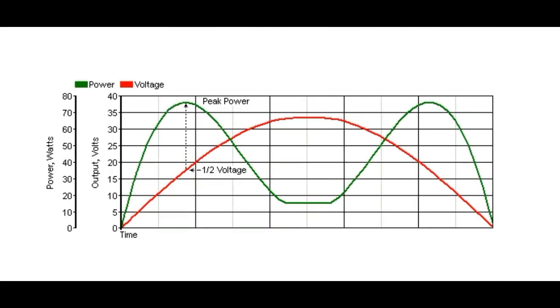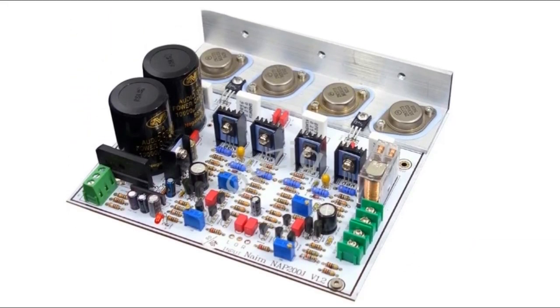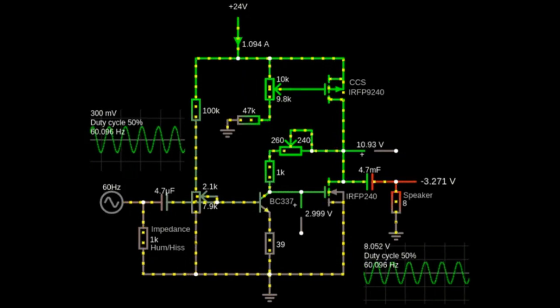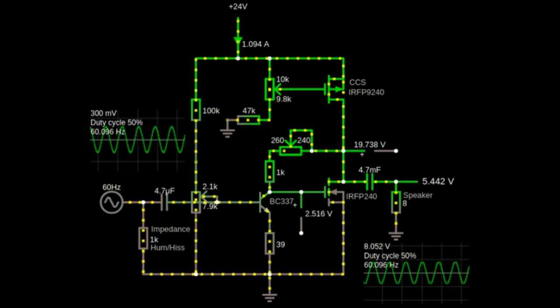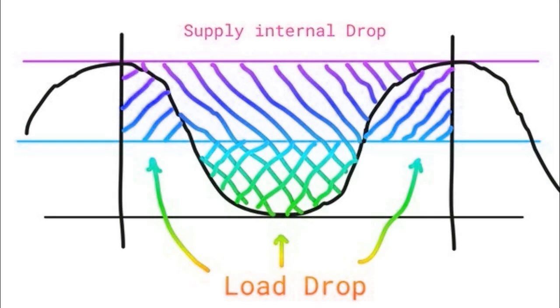Usually, the output transistor of a Class A amplifier gets very hot even when there is no input signal, so a heatsink must be used. When the output current is not established, the direct current of the transistor, IC, will be equal to the load current. A Class A amplifier converts most of the DC power to heat, so it is very inefficient.